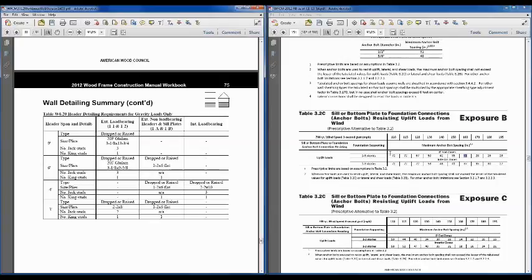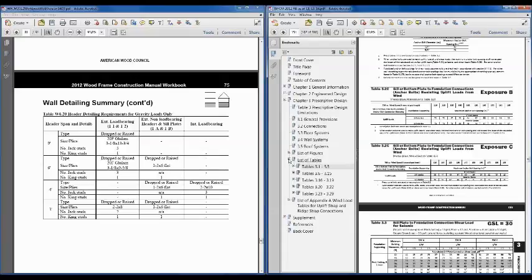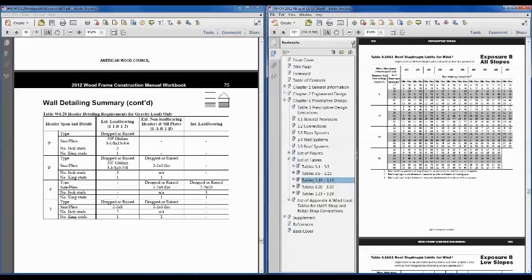Okay. So the wood frame construction manual does not cover force transfer around opening shear walls. You need to go to the wind and seismic provisions. There was a question related to perforated shear walls and whether or not strapping is required around the opening. No, that strapping is really part of the force transfer around openings method.